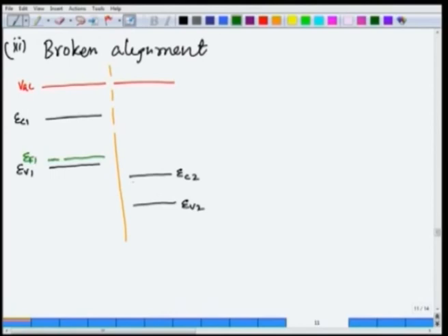Let us assume, so that the Fermi energy is here, p type, this is EF1, and let us take this n type, this is EF2. Deliberately I am doing that, otherwise the alignment will be too much off the screen, and hence it will be difficult. And this is psi 1, and this is psi 2. This is the electron affinity of the second material.